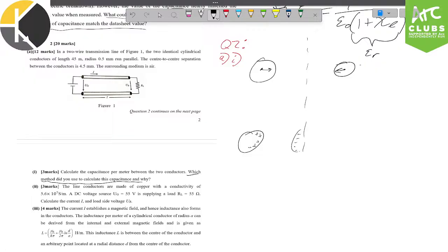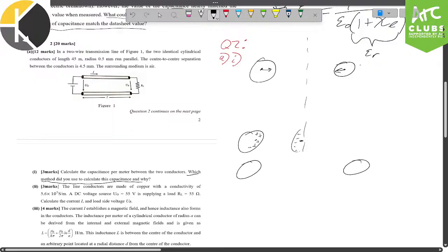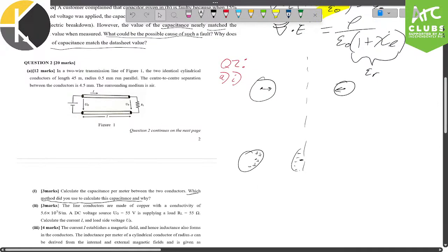All good? Is that where the assumption is that we have to put as much distance between them as possible so that... Exactly. So this effect of the charges clumping together when we have two close conductors with different charges can be chucked out the bin if we assume that they are sufficiently far away from each other. So this effect is negligible. However, in some circumstances, this will not be the case.